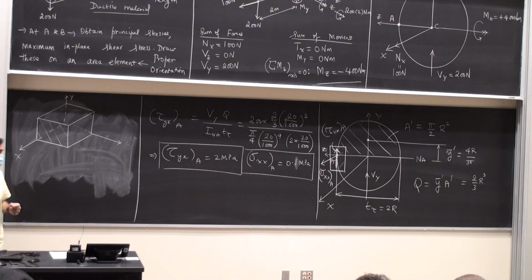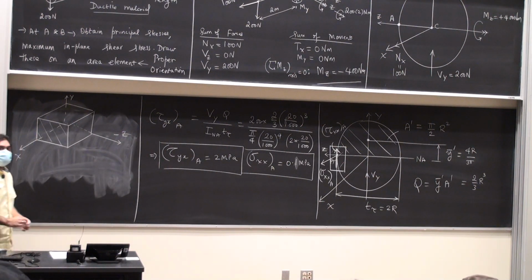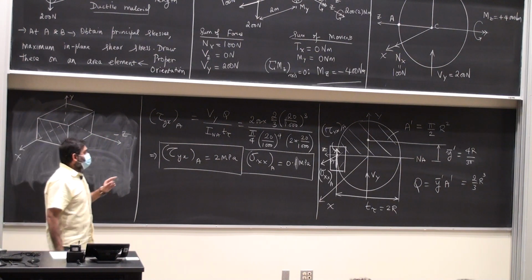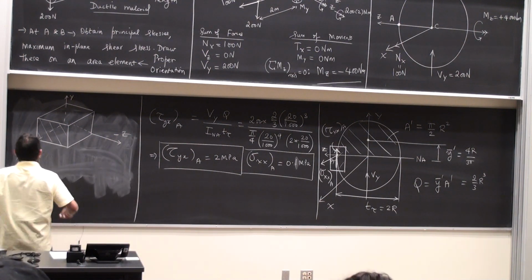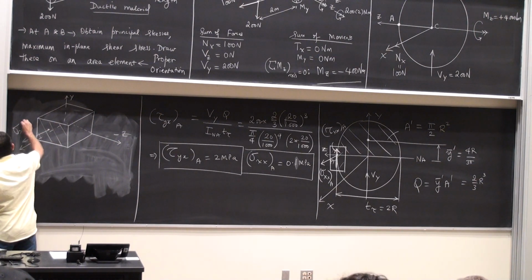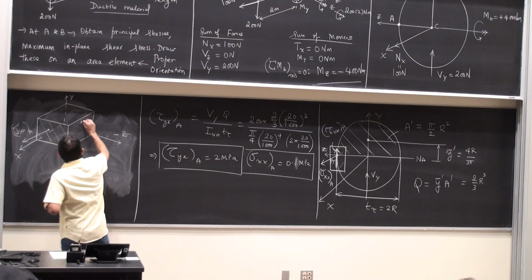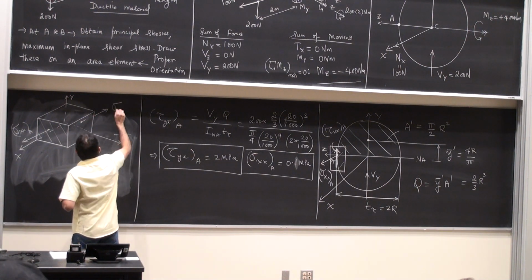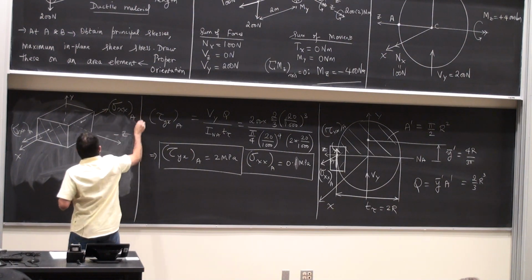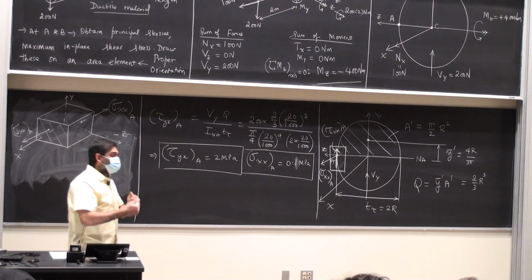On the other side. Okay? So this is the negative z. The positive z-axis is on the other side of the dotted line. I don't want to clutter my figure, already it's cluttered. Then I draw my sigma xx, my tau xy. Sigma xx. Front face, back face. At the point A. Then I have my tau xy, which is going to be a complementary state of stress.